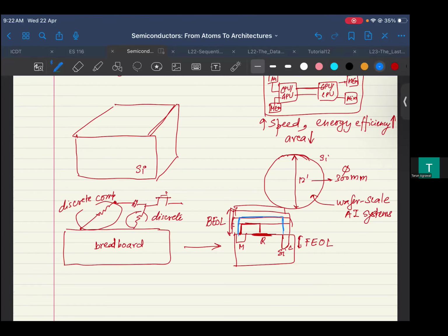And that is where, obviously, this is not done by a person anymore, right? These connections and everything, there are tools in the industry which we know as the EDA tools, right? And typically some of the physical design tools do this kind of thing. This is what we know as routing, right? Routing means connecting these different things and making sure that you meet the timings and everything which you want to meet.